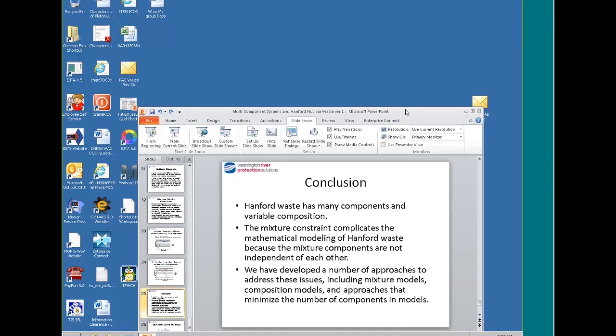I unfortunately used some letters that happen to also designate how likely a waste is to generate flammable gases, which is one of our largest safety, or I don't want to say safety concerns, but a lot of our safety controls are around controlling flammable gas buildup in our tanks. And type A tanks would be tanks that generate a lot of flammable gas, and type B tanks would be tanks that generate much less. Okay, thank you. So that would be an example.